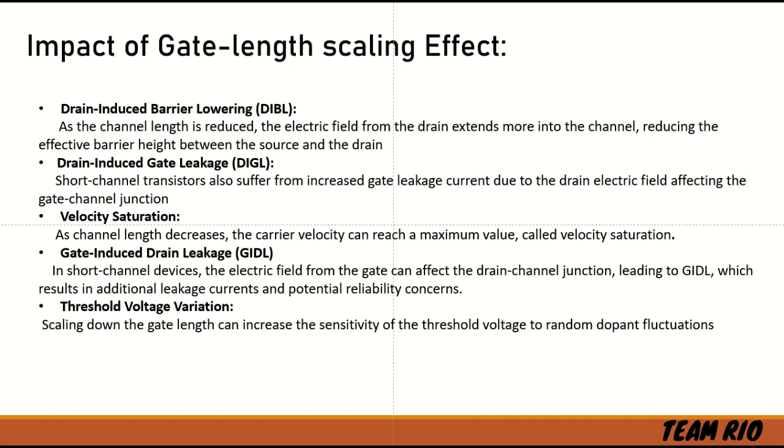The short channel effects refer to the deviation of transistor behavior from the ideal behavior as the channel length is reduced. Let's explore the impact of gate length scaling on short channel effects. Drain induced barrier lowering. As the channel length is reduced, the electric field from the drain extends more into the channel, reducing the effective barrier height between the source and the drain. This phenomenon is known as DIBL and it results in increased subthreshold leakage current, causing devices to operate in an undesirable state even when they should be turned off.